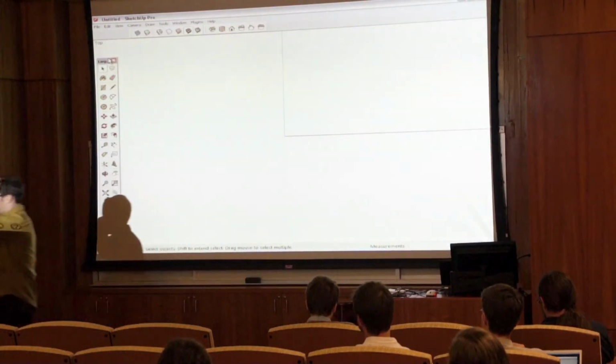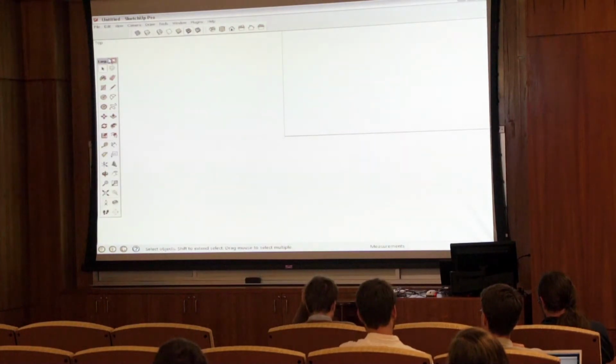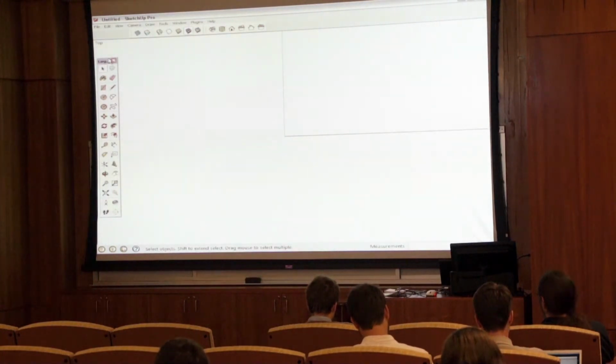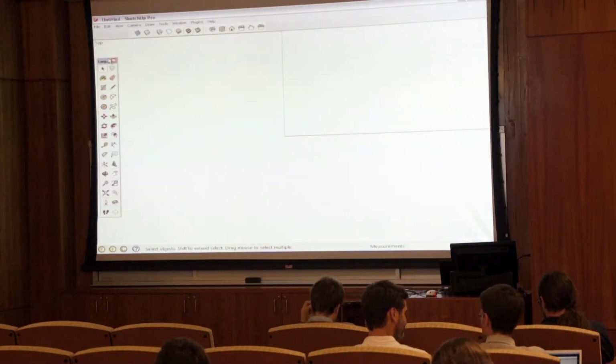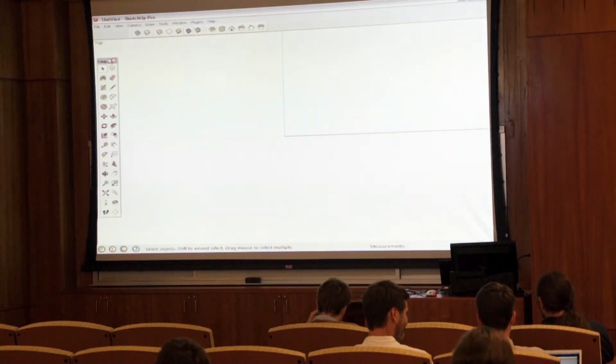For a Mac, it's a little more complicated in that you have to go to View, Customize Toolbar. Yeah, so there's two things. For a Mac, like you said, go to View, Tool Palettes and select the large tool set. That'll give you the large tool set to the left, but any of the tools up in the top dock, you have to go to View, Customize Toolbar, and basically drag out all of those top tools. It's sort of like throwing it out of the dock. And then drag up the Views and Styles palette, which I believe are in the top left.